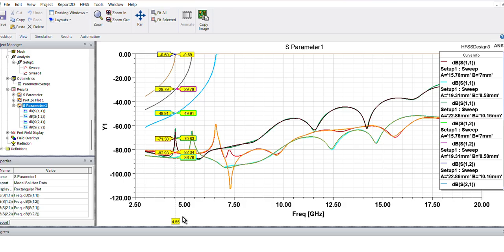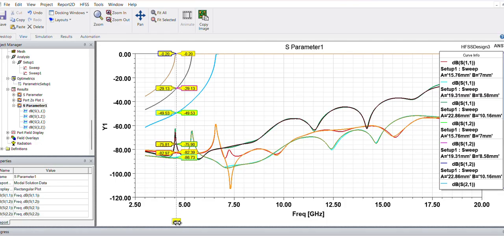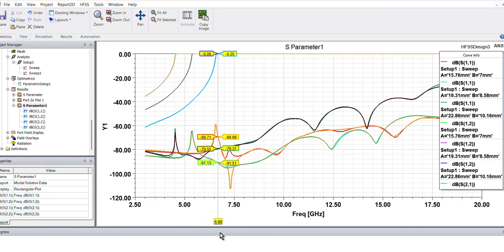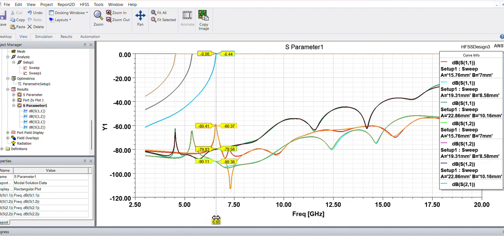Okay, you can see that when we are changing the impedance, different B and A combinations, our cutoff frequency is changing. And see, because we have maintained our 1.45 ratio, we have brought our cutoff frequency to the same 6.557 gigahertz.